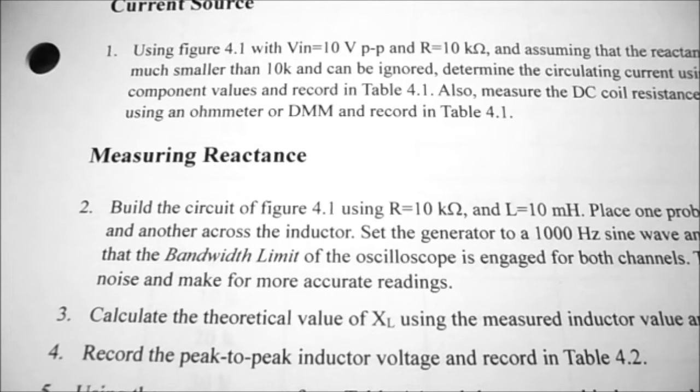And we're going to make sure that the bandwidth limit of the oscilloscope is engaged for both channels to reduce signal noise and to make for more accurate readings.